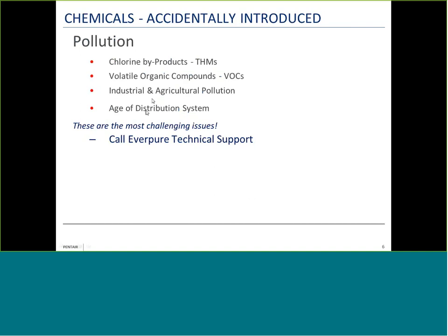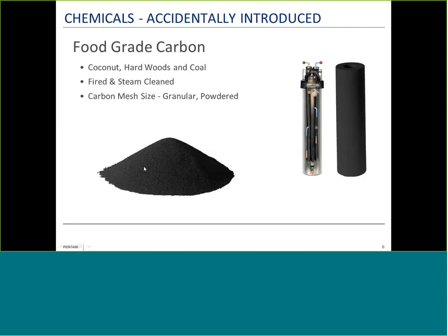There may be dead legs in the system that may cause biofilm to break off and travel downstream. These are the most challenging issues. If you run into problems with this, please call Everpure Technical Support or your local regional ops manager to help you through and specify correct solutions for these particular problems.